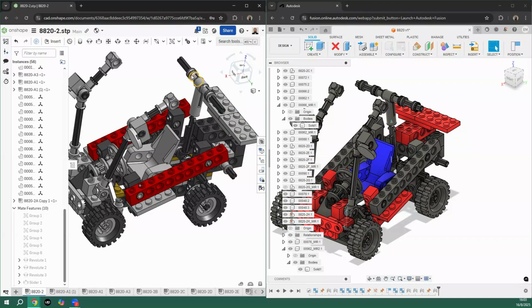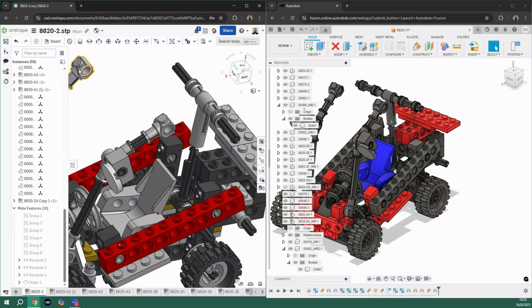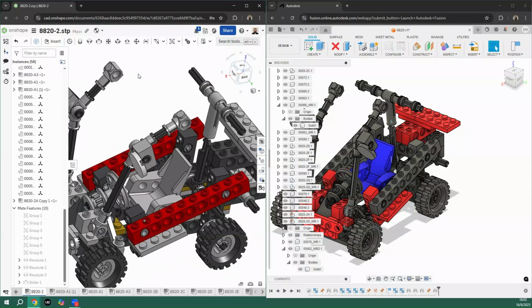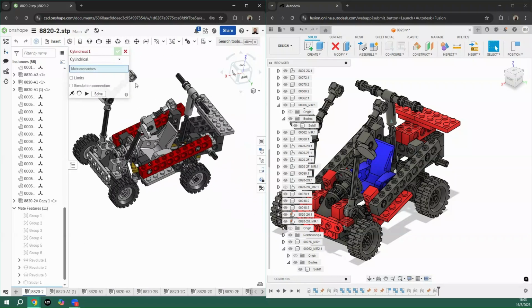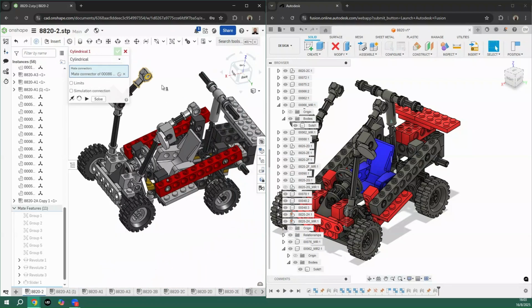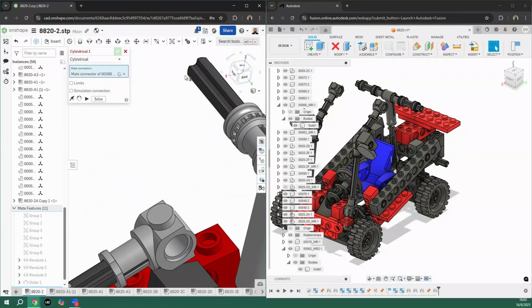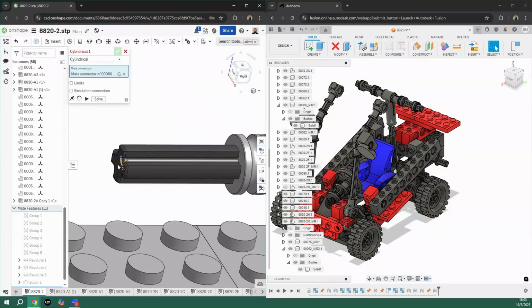Okay, so now let's get into the point where these two are going to be together: the arms and the pivoting piston, let's say, or the actuator. As a guess, what I need to do is a cylindrical mate. Allow translation and rotation about the z-axis. That sounds like what I need to do. Okay, so let's pick this, and now, well, I will pick this one, I guess.